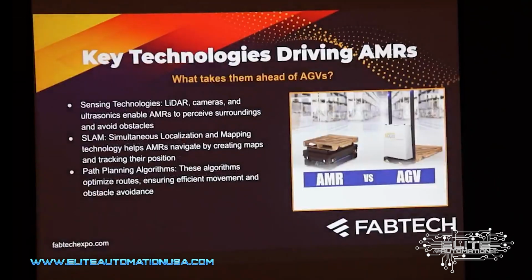Getting into the AMR versus the AGV a little bit, an AGV is built and travels utilizing a track system. So generally you have to cut and grout into the ground some type of magnetic strip. Sometimes you can use paint strips. There are different versions of AGVs on the market where their deployment is different between them. And as you can see, if you have to do any grouting of your concrete, that is a major implementation. There's a lot of cost there, and it's not very flexible. You're kind of stuck with whatever you have after you engineer and deploy it.